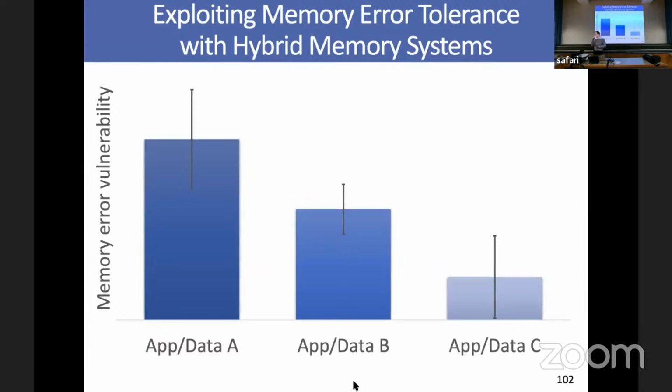But this is a general. If you look at this, I think we discussed this actually because there was some question in an earlier lecture. This is a specific mechanism that takes advantage of error tolerance of applications using heterogeneous reliability memory. So you have essentially heterogeneous reliability portions of DRAM. They offer you different reliability, and you map your data appropriately to different portions so that you can improve some metric. So this idea is actually relatively old.